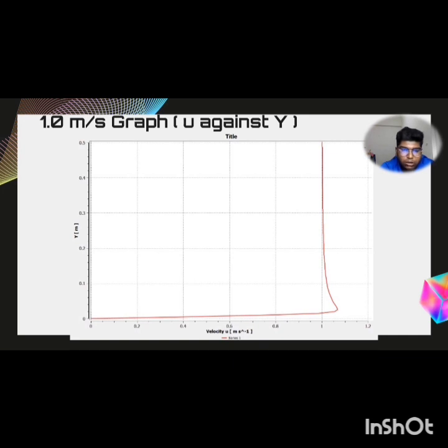This sudden spike could represent a boundary layer effect where the fluid velocity adjusts from a non-slip condition at the wall to the free stream velocity further away. The almost flat velocity distribution across the majority of the graph suggests a well-developed flow, which is typical in internal flow scenarios like pipe flow after sufficient run length.